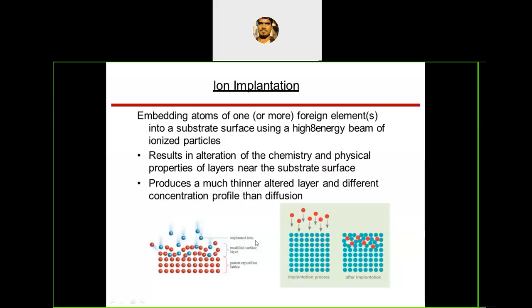So these are the implanted ions. Here this is a target. By providing energy, electricity, or heat, the target produces free atoms, and these atoms start implanting on the other, foreign surface. It is also depositing on the surface, into the substrate or on the surface. Both take place. So this process is called ion implantation.